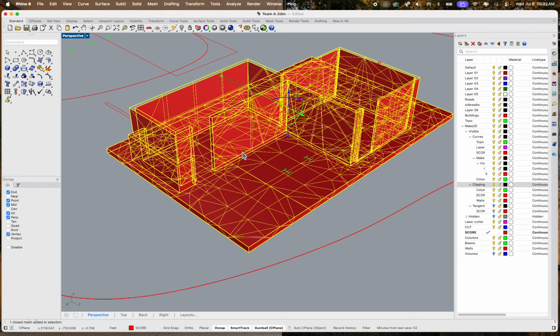I was just gonna say, would the more polygons make for a better 3D print or no? It does technically make it larger, and for instance right now we have only 90-degree angles. We don't really need more polygons. In fact, it won't change the quality whatsoever, just the file size. However, if you're doing Shrek's face, you may want more polygons because there's a lot more curvilinear edges. You may want to get his ears just right. You see what I'm saying?